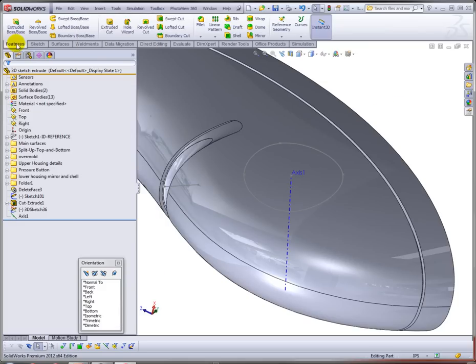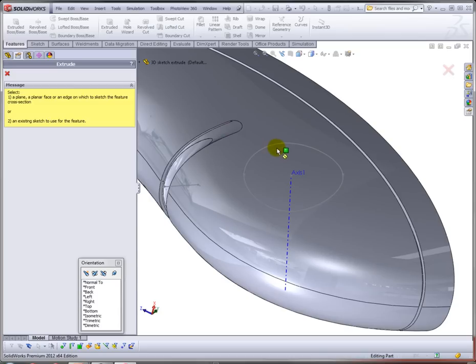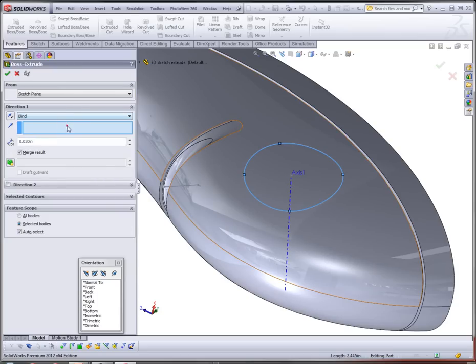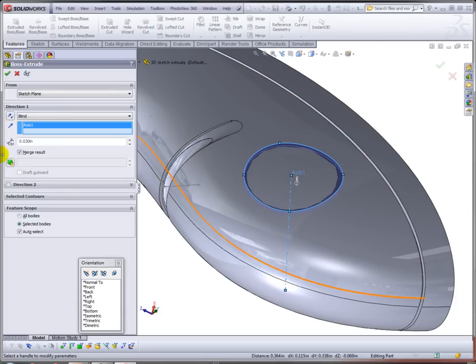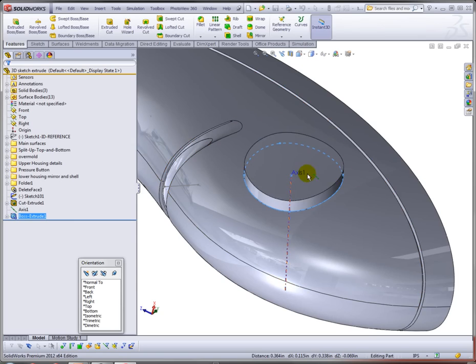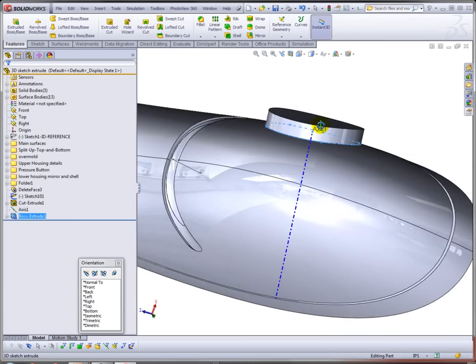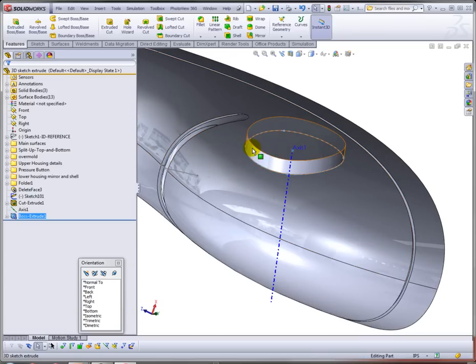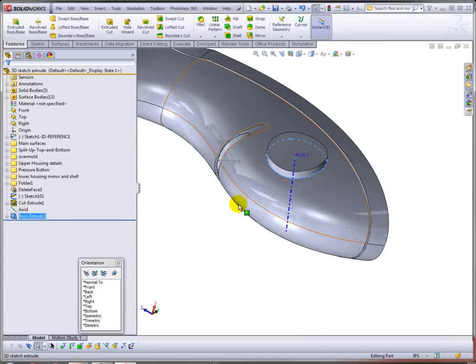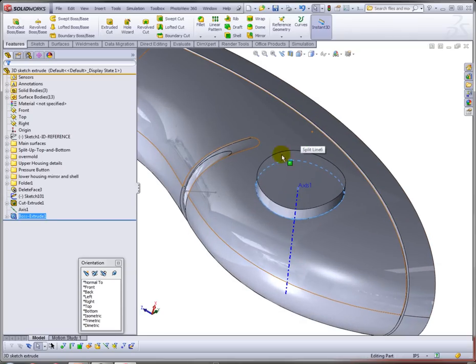And now at this point, I'll extrude this material using this sketch and this direction, going the opposite way. And now I can create some material here. You can see that it offset that surface, extruded it, and capped it using this direction. So that's really pretty handy without having to get into surfacing and creating that via boundary or loft or something else.